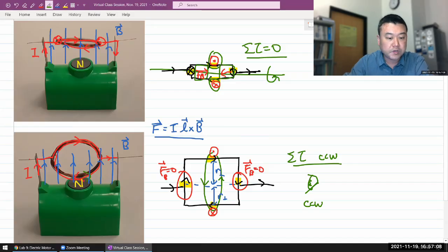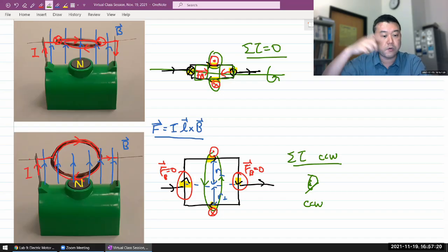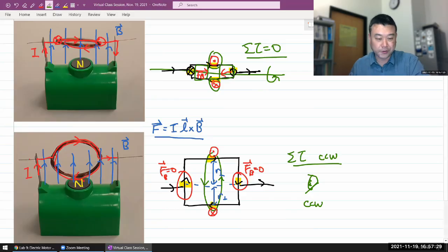That's why you need a bit of an asymmetry. In a practical motor, they have something called an alternator or commutator, something that will flip the direction of current as the motor turns, so that the net torque is in a consistent direction. For our world's simplest motor, all we have done is introduce a bit of asymmetry, so that in one orientation there will be torque, and in the other orientation there won't be torque, but the inertia will carry through. As long as the motor receives enough integrated torque over a full turn, it will continue to run, as you've seen in the demo.